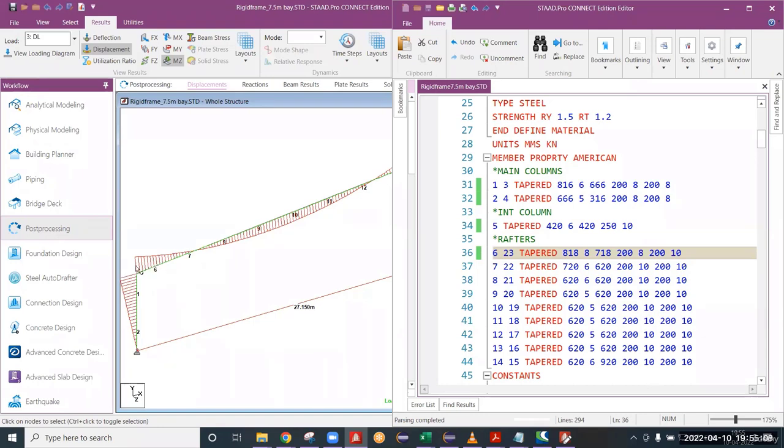Again, one doubt will come to you. Sir, can we change the thicknesses of the flanges from top to bottom? Yes. In PEB, it is acceptable to change the thicknesses of flanges from top to bottom. I'm reducing the thickness at the top here. If you observe member 7 also, you can follow the same.